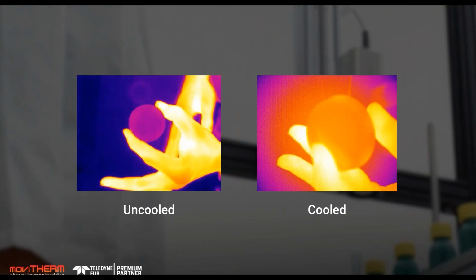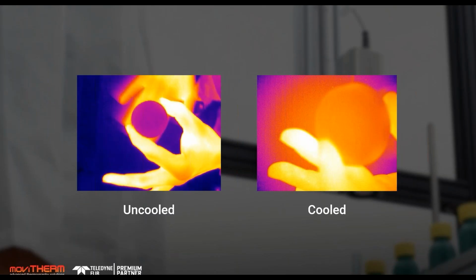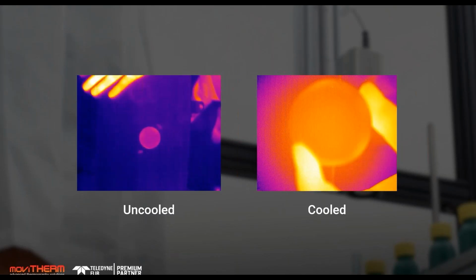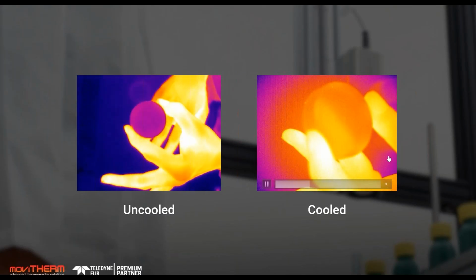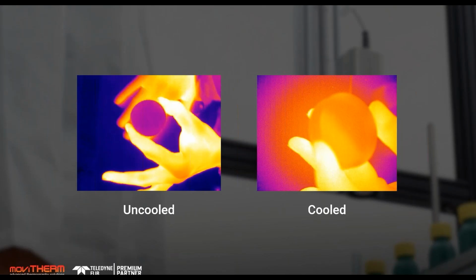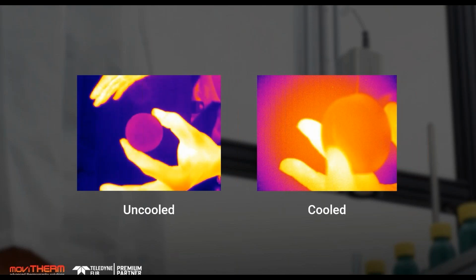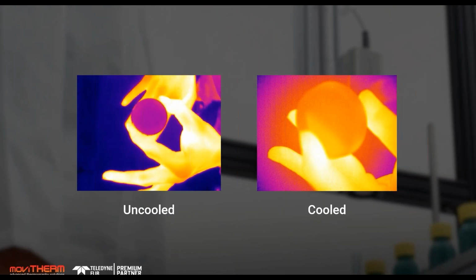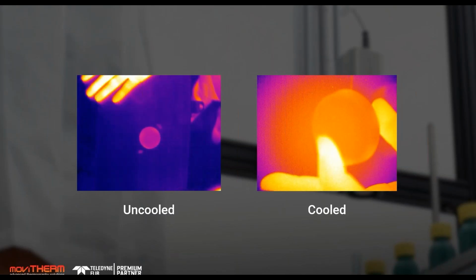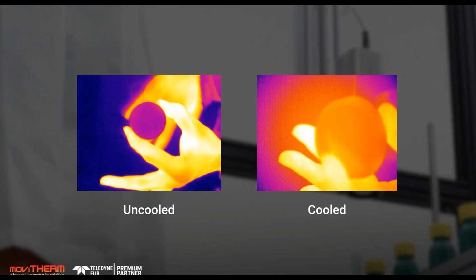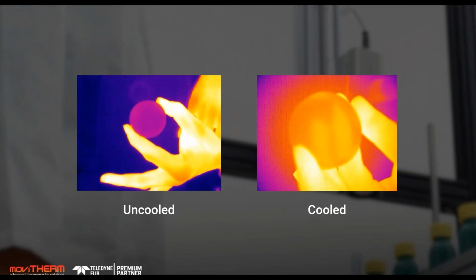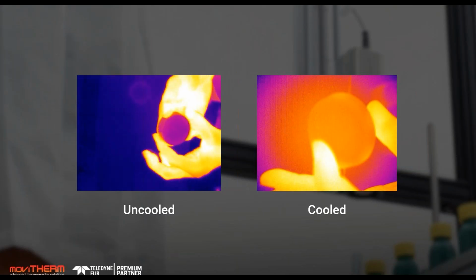Now, there are cap configurations that are challenging. So child resistant caps, dispensing caps, flip top caps with an extra layer of plastic. With CRC caps, they have an air gap, and that essentially stops the flow of heat to the top of the cap. So in situations where customers have these type of cap configurations, we go with a mid-wave camera. And again, mid-wave and cooled are somewhat synonymous.